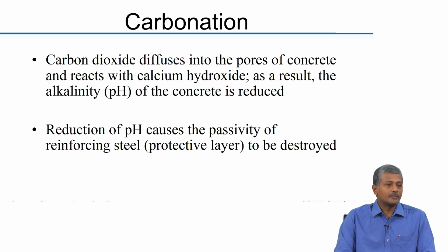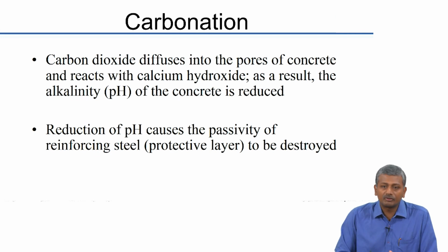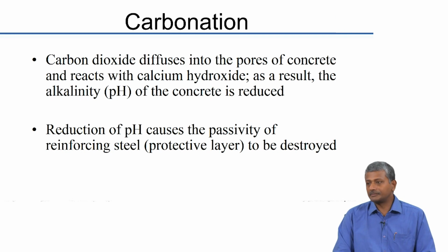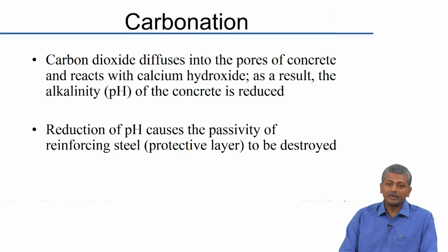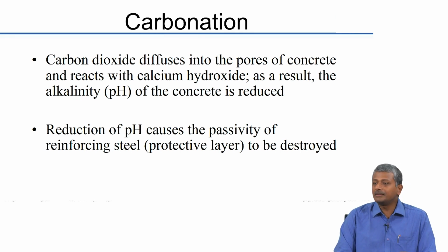is carbonation. Now, we have talked briefly about carbonation earlier. We talked about the fact that whenever you have mineral additives in concrete, they tend to reduce the amount of calcium hydroxide available in the system, and that buffer, the alkaline buffer that you remove from the system, often is responsible for a greater depth of carbon dioxide penetration into the system. Okay. So, CO2 attack is generally higher whenever cement is replaced by mineral additives that tend to bind the calcium hydroxide into pozzolanic CSH.